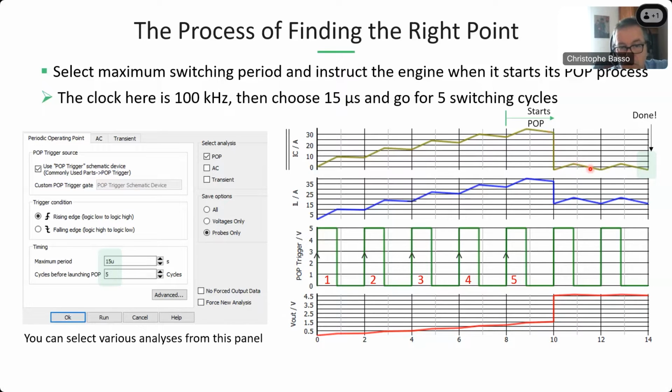So the average current on the capacitor is obviously 0 here, and the steady state current value has to be at this final DC average value, which is given here, and the voltage has reached its final value, which is around 5 volts. So setting initial conditions, of course, to bypass soft start sequences, for instance, helps converge faster to steady state.